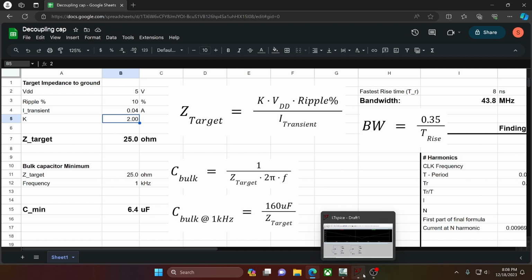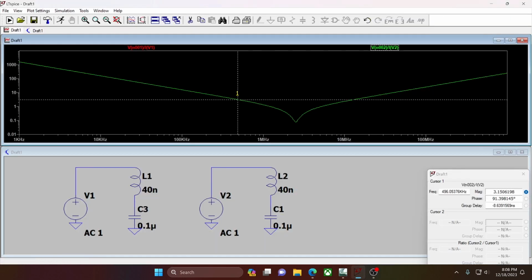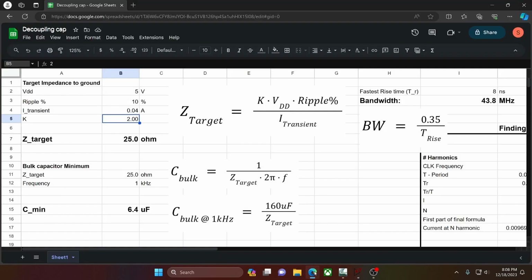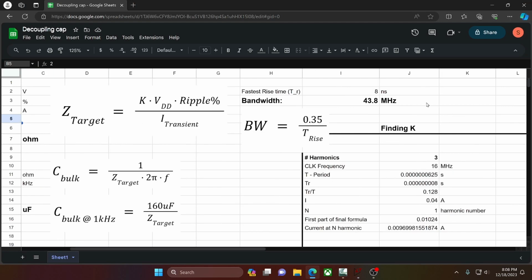Now we're talking 25 ohms. All right, let's go up there then. So we're at 25 ohms with the crappiest connection to our IC you could have. I suppose you could do worse, but you'd have to try. We don't want to try. So right now we're at 62 kilohertz. And over here we're at 100. So your question is, wait, what's going on? Is this 100 okay? Well, if we go back, we look at this formula.